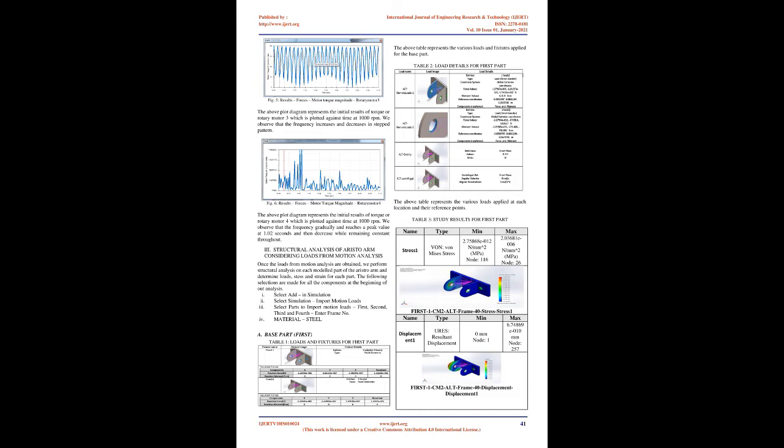Pro/Engineer is a feature-based program used for parametric solid modeling. As such, its use significantly differs from conventional drafting programs. In conventional drafting, which can be either manual or computer-assisted, various views of a part are created in an attempt to describe the geometry. Here, each view incorporates various featural aspects like surfaces, cuts, radii, holes, and protrusions, but the features are not individually defined, while in feature-based modeling, each feature is individually described then later integrated into the part.